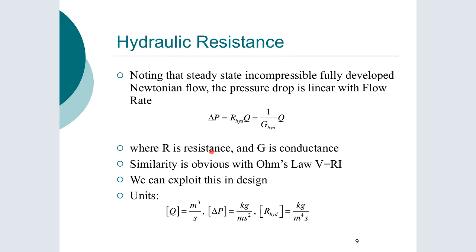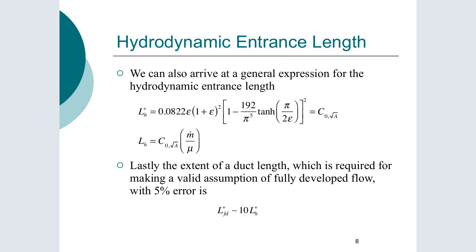So this will be a short lecture this morning on hydraulic resistances in microfluidics. In the previous lecture, what we looked at was a general expression for the pressure drop in channels of arbitrary cross section. And as part of that, one of the things that we were able to derive was this expression here, which gives us a calculation for the hydrodynamic entrance length. And that's the region where the flow is developing.